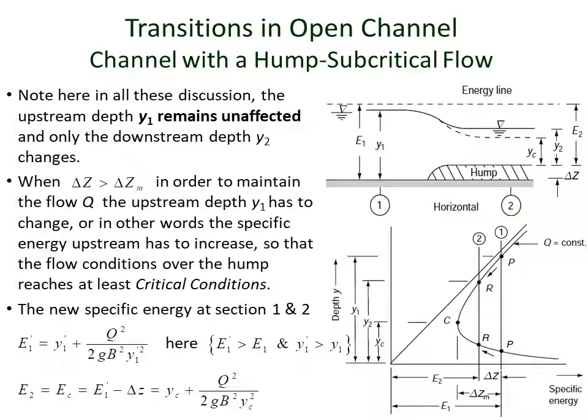Now, to continue the flow, something has to change, and that has to be the flow depth. For the same discharge Q, if the flow has to happen, then the upstream flow depth y1 has to increase. If the upstream flow depth y1 increases, the specific energy of flow increases, so that the flow can again continue.